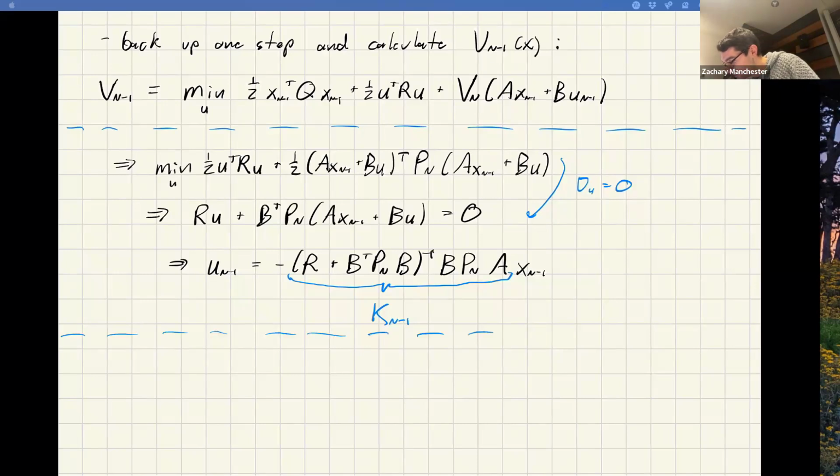The fact that we're able to do this for any general x_{n-1} is because of the LQR setting, because of this temporal structure. The fact that I can do it in closed form and that it ends up being a linear policy is a property of LQR. But in the notion that we take a state and try to optimize from that state, if you want to do it for any general state, well, dynamic programming usually does it for the general any-state case.